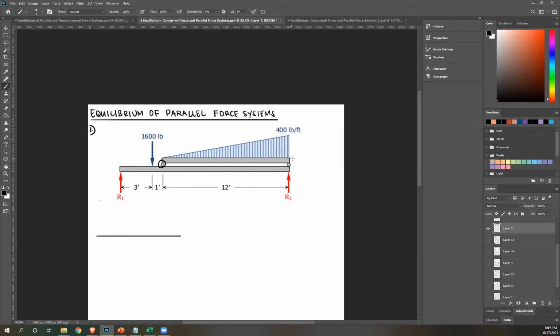As you can see, these drawings show or indicate rollers, right? Whenever you have supports, and roller is a type of support, there's gonna be a reaction there. So there's a reaction here, okay? And then you're gonna guess the direction. Usually, if your loads are downward, the reactions are upward, okay?